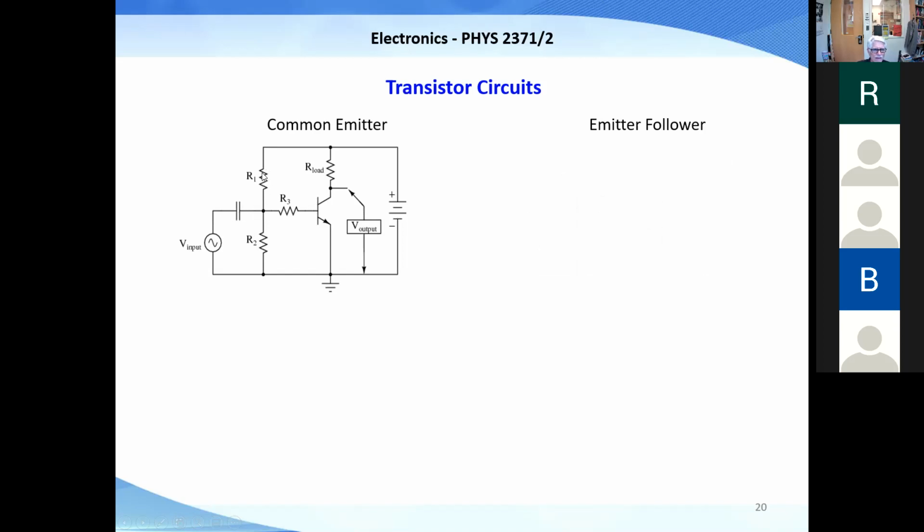And then you have another voltage divider here. So you have some voltage bias here, but you have a signal coming in, adding to that voltage bias. It goes through this resistor and it changes this resistance. So then the voltage output you get out of here is proportional to what you're going to put in here.